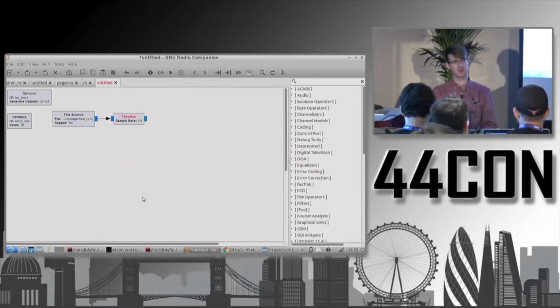So basically I'm going to walk you through making an on-off keying demodulator, but I'll also mention that the flow graph from yesterday that we're going to release is just as good. So you'd be able to replace the values there, and maybe that's what we should do. Should we? Yeah, let's pull that up and just tweak the numbers. It's probably easier. On-off keying is one corner case in GNU Radio where there's no out-of-the-box flow graph or module or block for doing on-off keying demodulation. So we have to actually build one in this case.